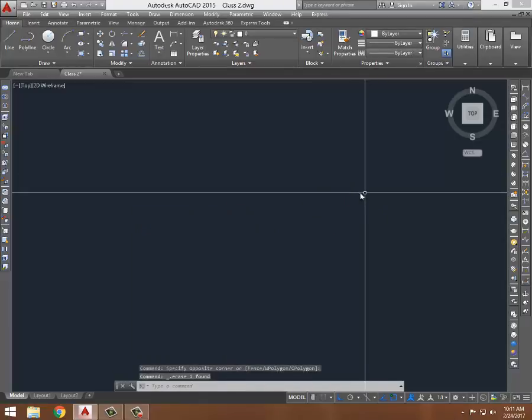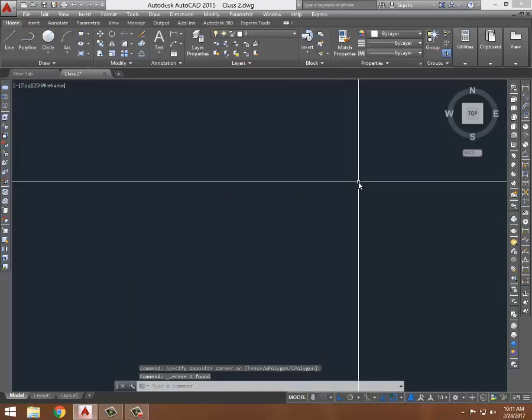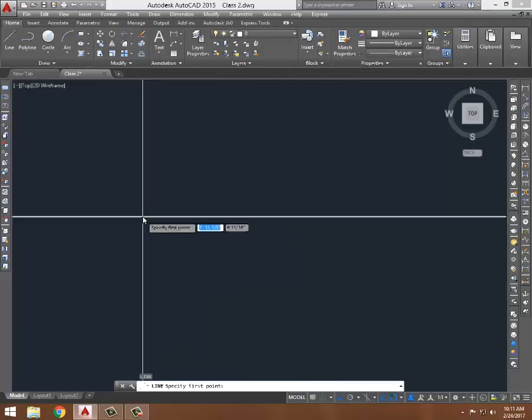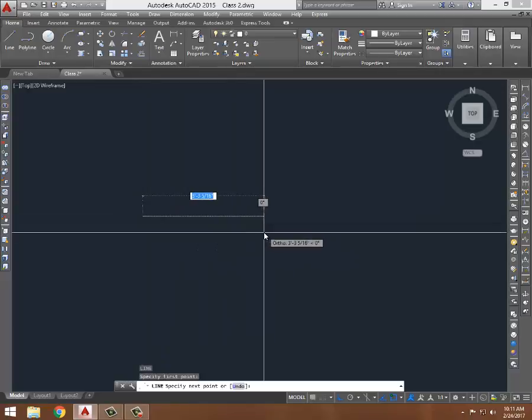So now we will draw a line with dimension, because in AutoCAD whenever you work you need to draw lines in dimensions. So L, enter, click. I'm just dragging, but I'm not clicking, because if I put the dimension I do not need to click. Say this line I want to draw as 48 inches. Now we can provide the dimension two ways. Right now let's go with 48, then enter, then enter.